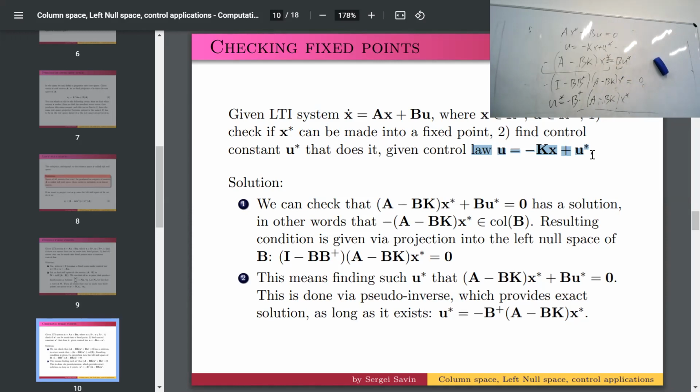This will change the control signal. Hmm? This will change the control signal, A minus BK. Would change what? The control signal that's going to the... No. The solution doesn't depend on it. Here is the solution, here is the check. Why do we need the check? To make sure B is invertible. It is not invertible. B is almost never invertible. But you are very close to the correct answer.